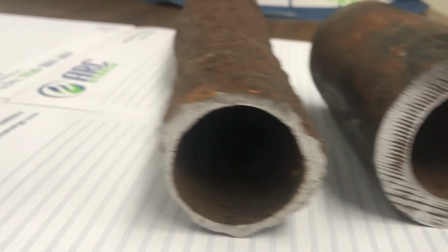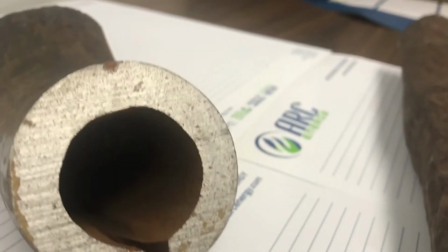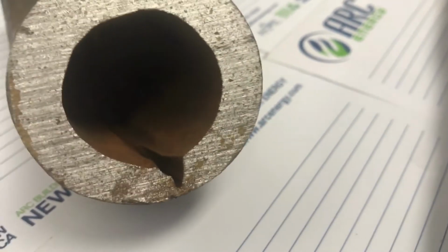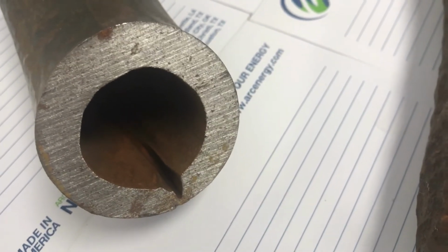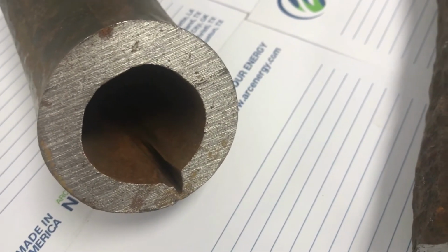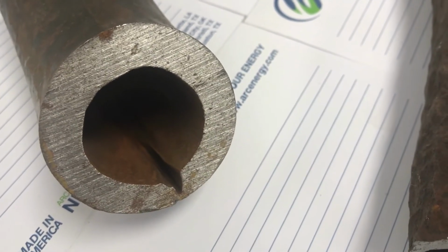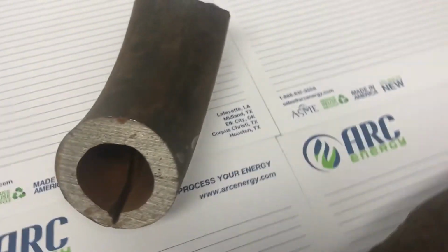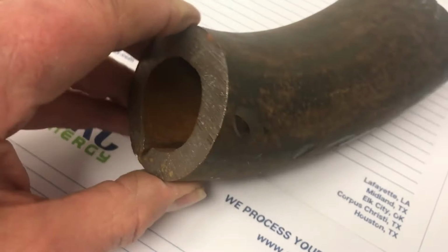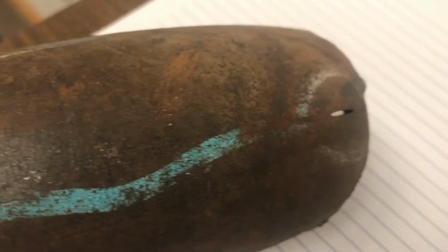Then this is an example of erosion, which in this case is internal. In this case, the flow was extremely fast with some solids, and once that groove started, it was like a funnel and funneled all of the erosive materials to the outer edge of this elbow. It actually ate clear through in spots. But that is erosion